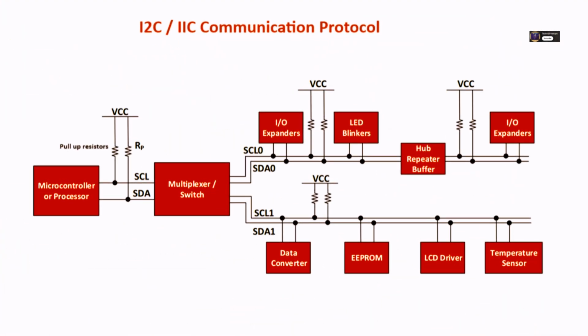I²C is everywhere in embedded systems, reading environmental sensors, temp, humidity, light, pressure, accelerometers for smart homes, wearables, industrial controls, storing settings in EEPROMs, controlling power management ICs, PMICs, in laptops, phones, anything battery powered to manage voltages and save power, talking to small displays, OLEDs, LCDs, and gadgets, appliances, medical devices. Its sweet spot is really those low to medium speed, short distance links inside a device where minimizing pins and wiring is key. So, given that short distance is important, what are the practical hardware limits?